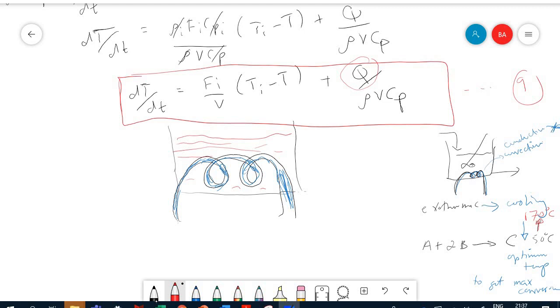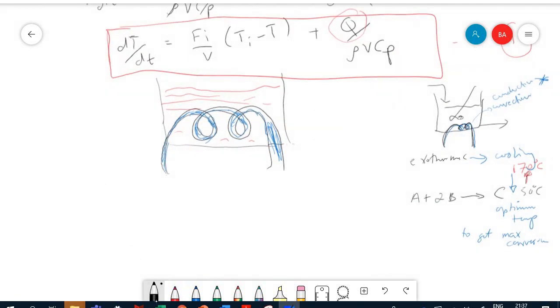But because the wall thickness is very small, we cancel that conduction term and it becomes easier, and our Q will simply be represented as a general term. We call it U, the overall heat transfer coefficient, but just not to confuse you with the internal energy, which also uses U. So this is the U for the heat transfer.